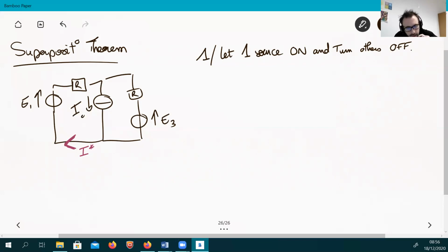When you turn a voltage generator off, a mnemonic way of remembering how it works is like erasing the circle. If you erase the circle on the voltage generator symbol, you end up with a wire. So when you turn off a voltage generator, it's equivalent to having only a single wire between your 2 points.